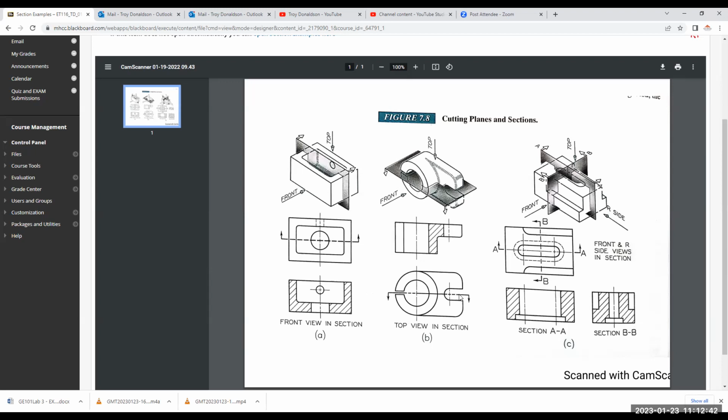This is good, right? It's the big dash line for section BB. And we do label them. They're labeled on each arrow, AA, BB, CC. And then when you label the drawing, you call it out as section AA, section BB. Sometimes you'll see three, four, five sections on a drawing, and that's just so we can see inside the part. Like you'll see front, top, side view and section AA, section BB, section CC, and it's just giving you a view inside to the guts.